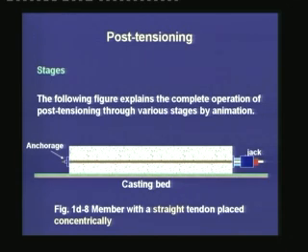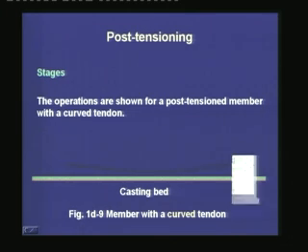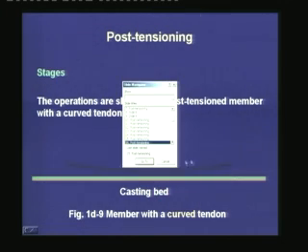Now, once these are placed in position, the tension is applied by the jack, and you can see as the jack applies tension, the concrete undergoes the elastic shortening. And next, okay, before I go to the next one, let me show the previous animation once again.